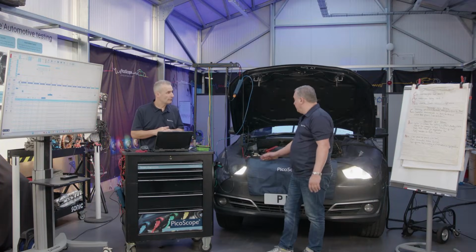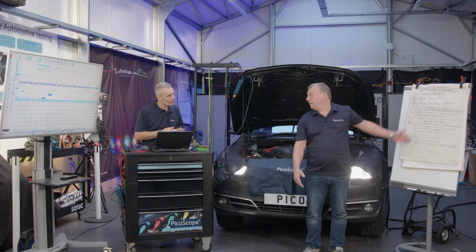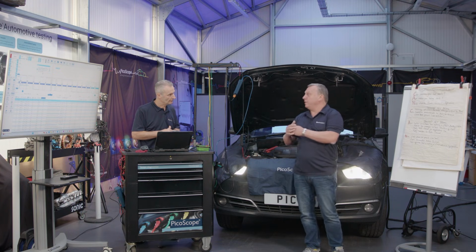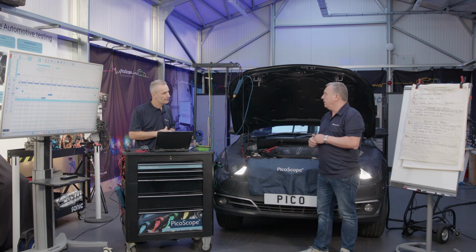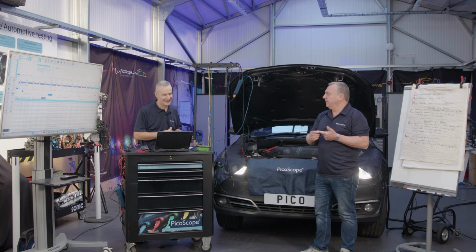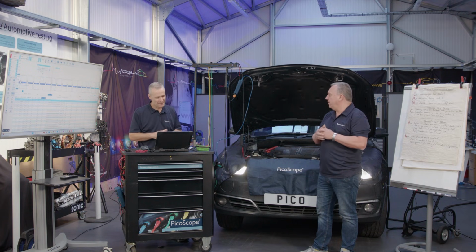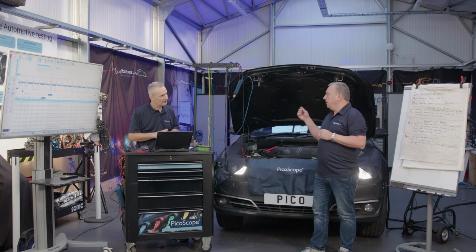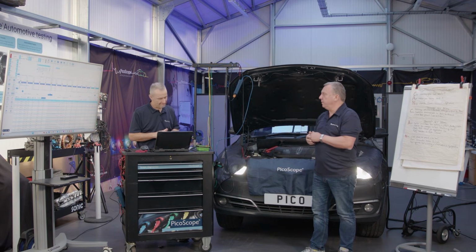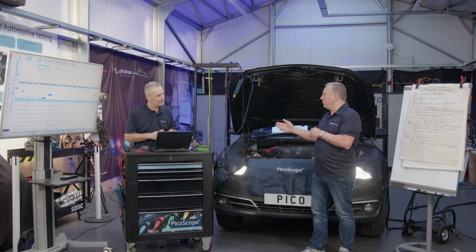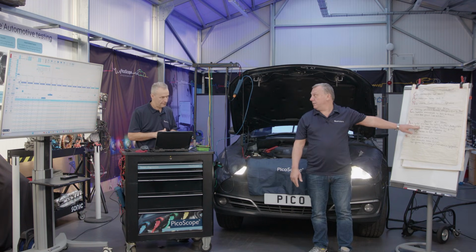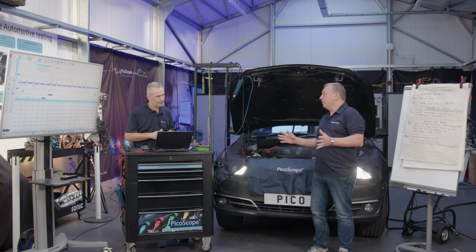I think once again, Steve, we've proved that using the CAN process for network diagnosis, we're really concentrating on the messages being sent. We've demonstrated a number of different techniques, the good, the bad, and the damn right ugly of measuring high-speed networks. But I think the differential probe at the end shows that you can use one channel and get all the same information, because whatever happens on either one of the twisted pairs will affect that. Once you see something that's wrong in the messages being sent, that will give you everything you need to know with a single connection.